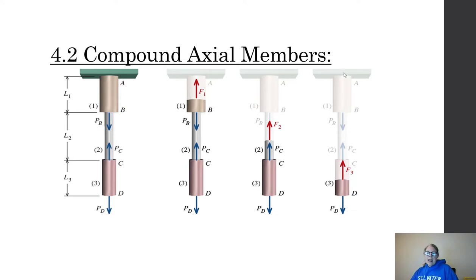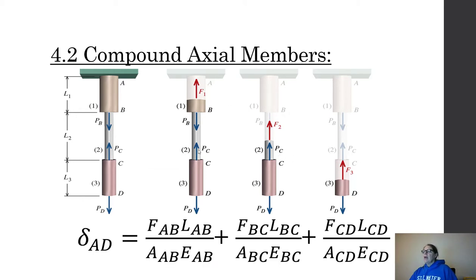I would have to find the reactions. So if you have a free end, which we call like a cake problem, it's got a free end, start at the free end and then you don't have to find reactions. Then keep up with, am I in compression or tension? You just sum up those deltas so that you can get an overall change in length.